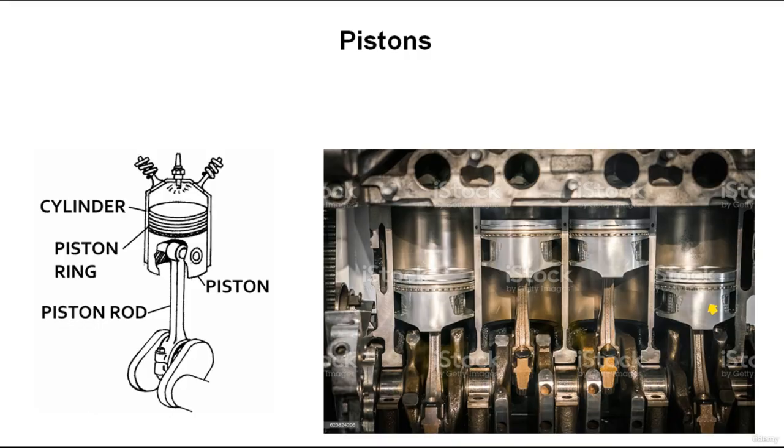Also, let's discuss right now the piston. The burning of air and fuel takes place between the cylinder head and the top of the piston. The piston is a can-shaped part closely fitted inside the cylinder. In a 4-stroke cycle engine, the piston moves through 4 different movements or strokes to complete one cycle. These 4 are the intake, compression, power, and exhaust strokes.